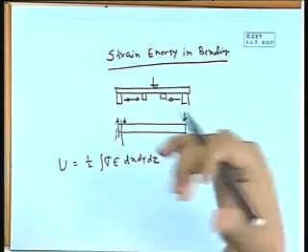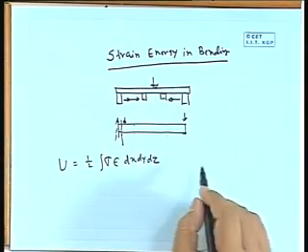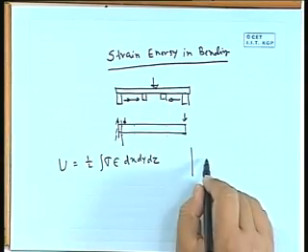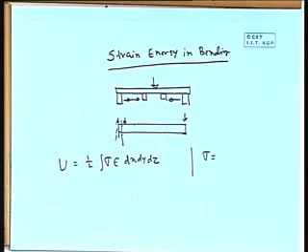So, we are putting it in a separate form, and here this sigma for a bending problem we know it is My by I, so it is depending on y. If x is the coordinate along the length of the member, along the axis of the member, y is perpendicular to that along the depth, and z is along the width.